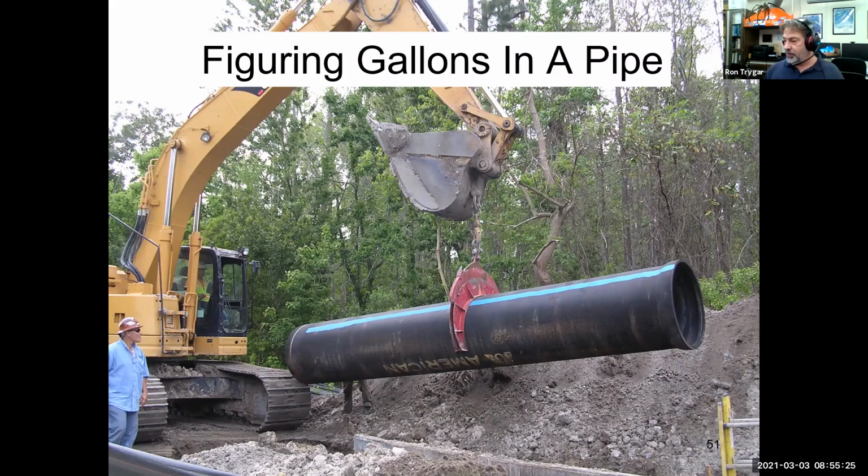The volume of water capacity that could be inside a pipe like this, or inside of a storage tank like I just showed you, the volume of water is important because we're going to be dosing chemicals into these shapes, and that's going to be for disinfection purposes for sake of a water distribution exam, or even for calculating, say, gallons per second of water moving. So we need to know the gallons for several different reasons.